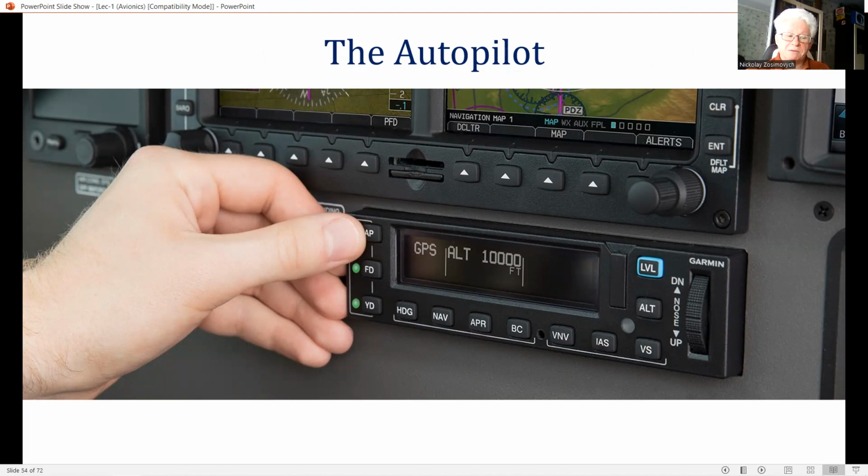Apart from the basic modes, such as height hold and heading hold, a suitably designed high-integrity autopilot system can also provide a very precise control of the aircraft flight path for such applications as automatic landing in poor or even zero visibility conditions.